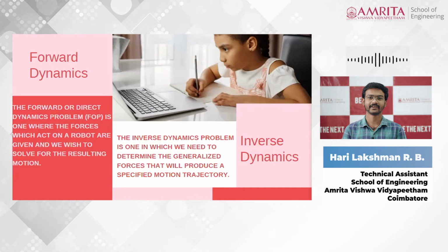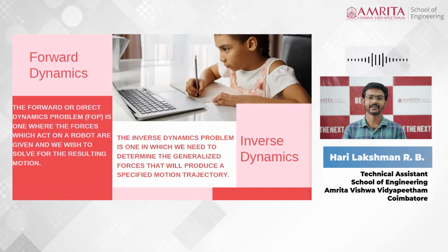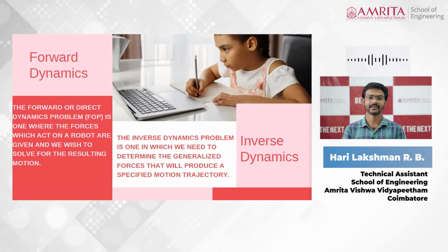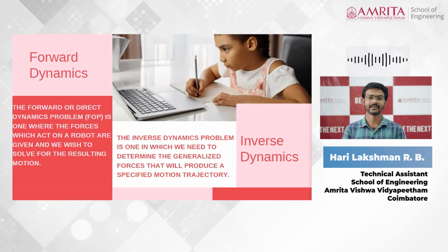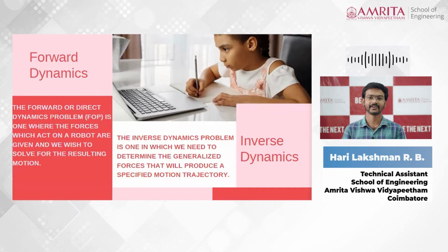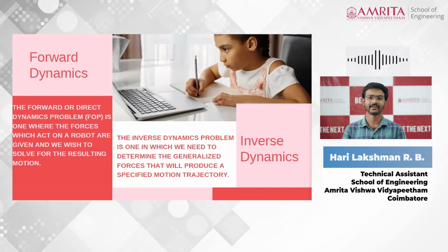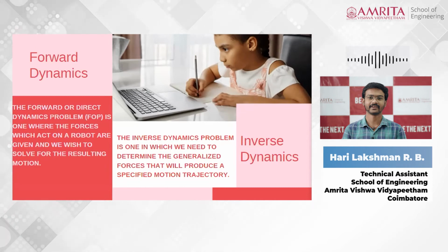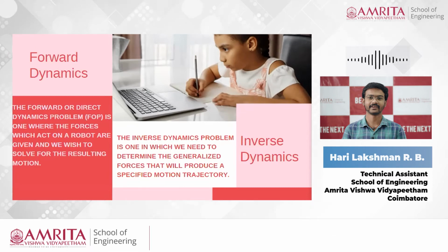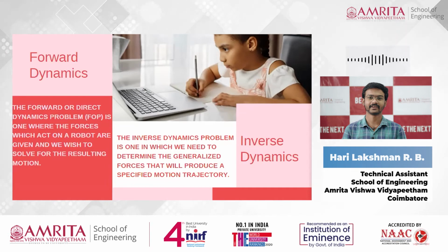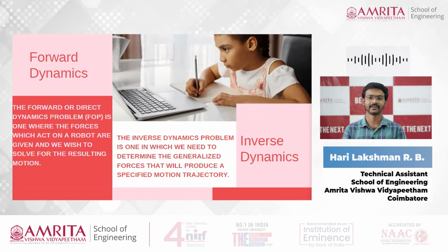We can't risk the manipulator damaging itself or damaging the other users or the other controllers which control the manipulator. That's why the simulator is used, and robot forward dynamics is vastly used in simulations because we can give whatever kinds of forces and constraints to a robot, and we can see in the simulation in what direction the robot is being moved or being held up.